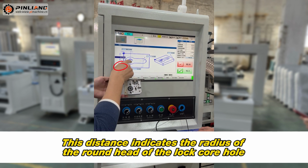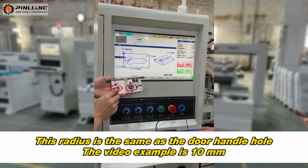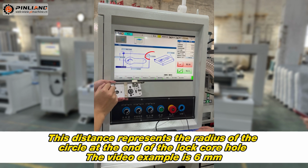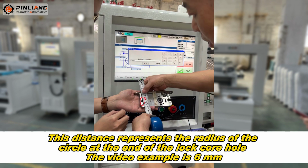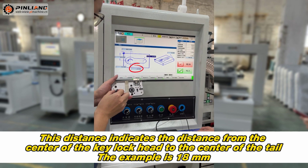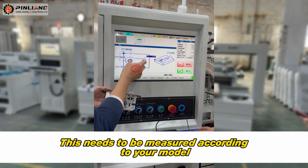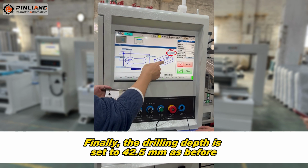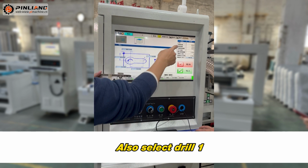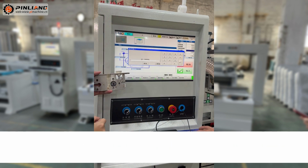This distance indicates the radius of the round head of the lock cylinder hole. This radius is the same as the door handle hole. This distance represents the radius of the circle at the end of the lock cylinder hole. This distance indicates the distance from the center of the key lock head to the center of the tail. This needs to be measured according to your model. Finally, the drilling depth is set to 42.5 mm as before. Also select drill 1. The number of drilling divisions is 3 times.